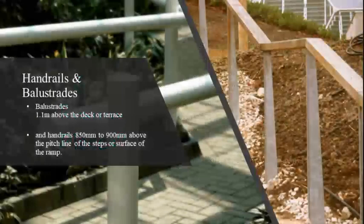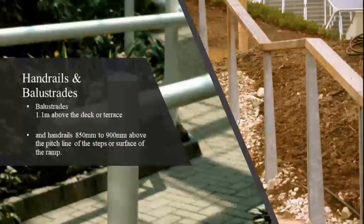The purpose of a balustrade or guardrail is to provide a barrier to protect a change of level. A handrail, on the other hand, is primarily to assist the climbing or descent of a ramp or flight of steps by providing a handhold, but it may also act as a guardrail. The risk of falling needs careful assessment.